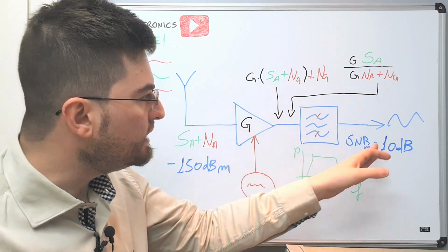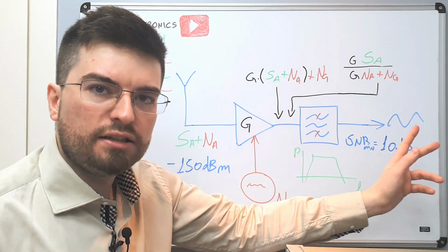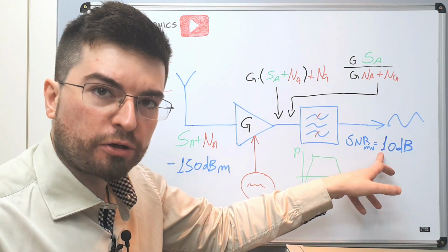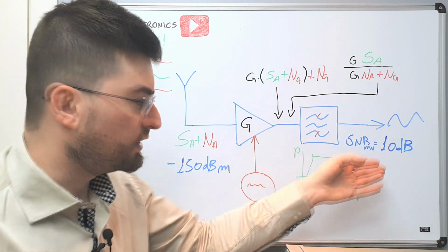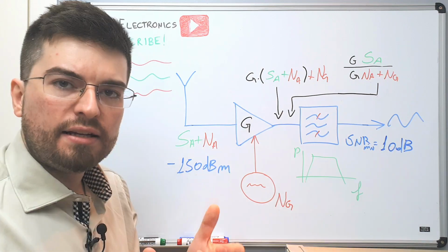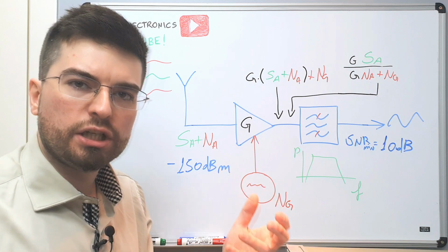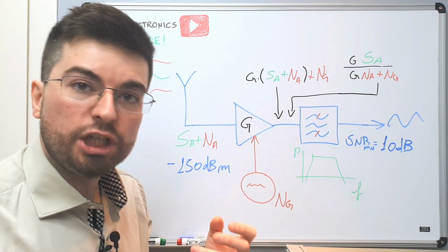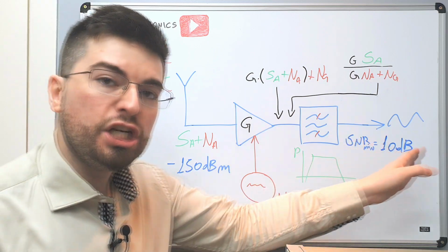And of course, guys, different modulations and different forward error correction codes will change this figure. So we can have receivers that work with a 3 dB signal to noise ratio, a 1.5 dB signal to noise ratio, and it basically changes with the different modulations used, and also, very important, with the amount of computation and latency that the digital step can take.